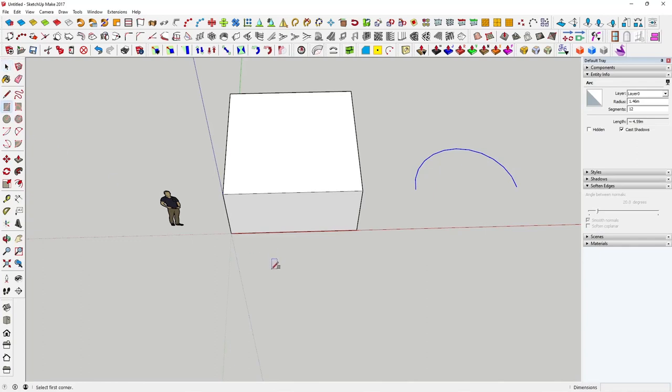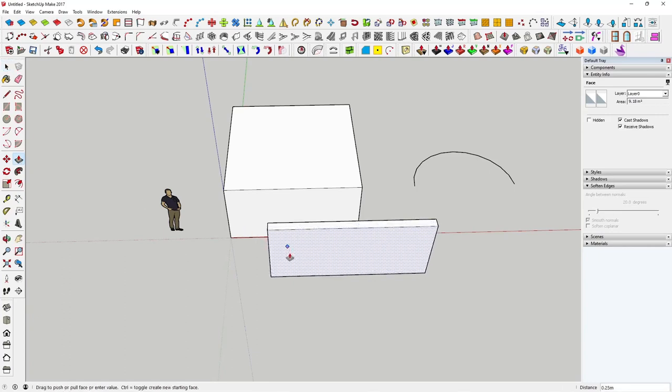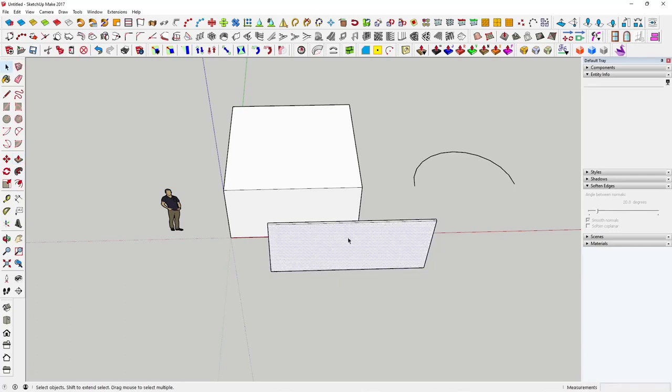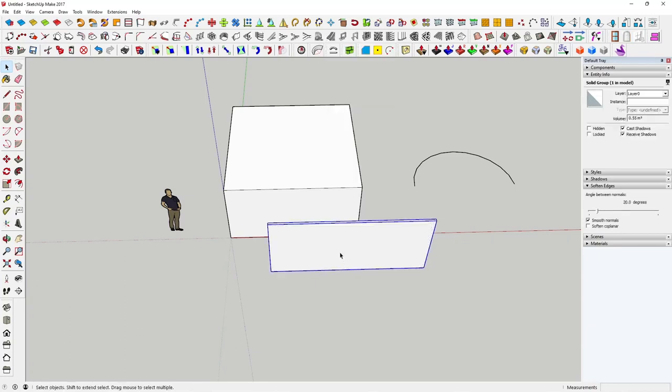So we go to the rectangle tool, press the left key, green axis, up, it'll be 4.59, comma, and because it's 20mm thick, it'll be 2, enter. Click on the front, push pull, pull it towards you, 0.06, enter. Pick tool, on the face, copy. Triple click, right click, make group.